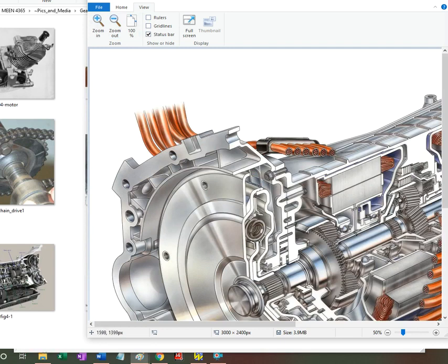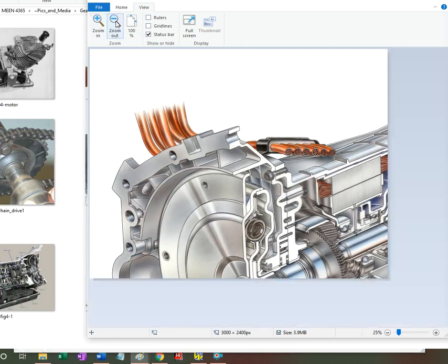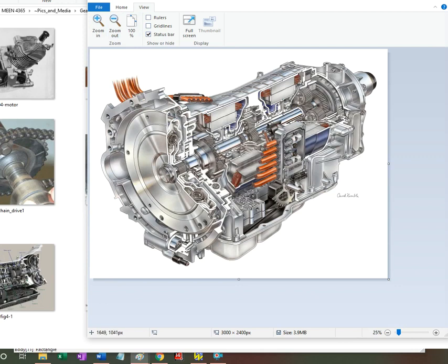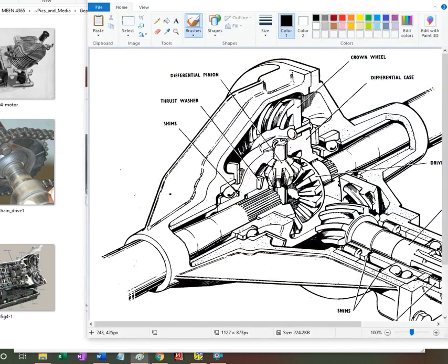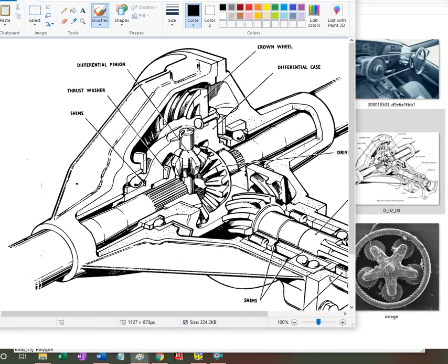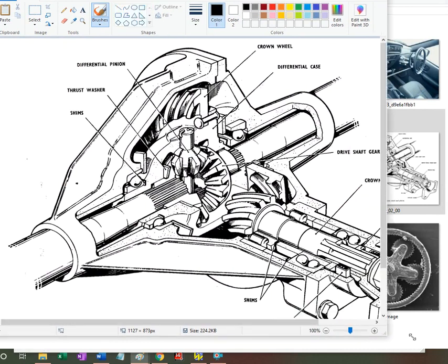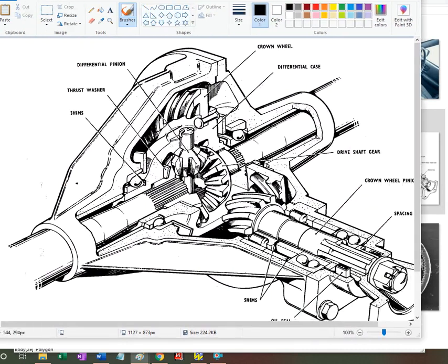With the planetary gears, the planetary gears part of it looks like this one has 3. And then the most common of the differential gears or planetary gears would be the car differential. So you have the input pinion, a gear we call the ring gear, same as with planetary gears, but this is part of a bevel pair. And then you have the planets, and you have the 2 sun gears.